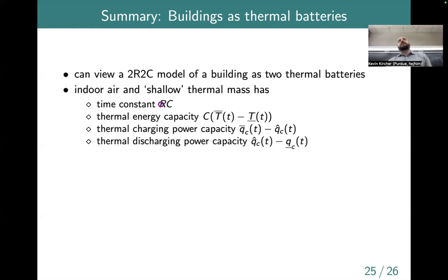So the question is, suppose you're using a heat pump, and maybe a heat pump that you can reverse the cycle and provide cooling, but you're using it for a space heating application. Electric heat pump. Would there ever be value in doing thermal storage for that application as opposed to electrical storage? Even if it were ice for HVAC, if you could just run a heat pump to take heat out, does it ever make sense to make ice?